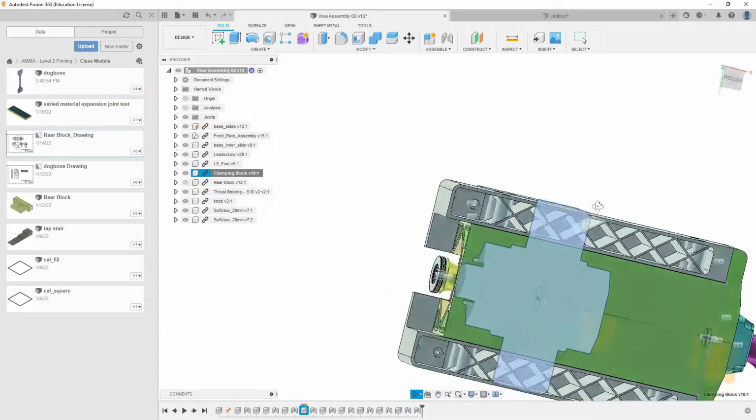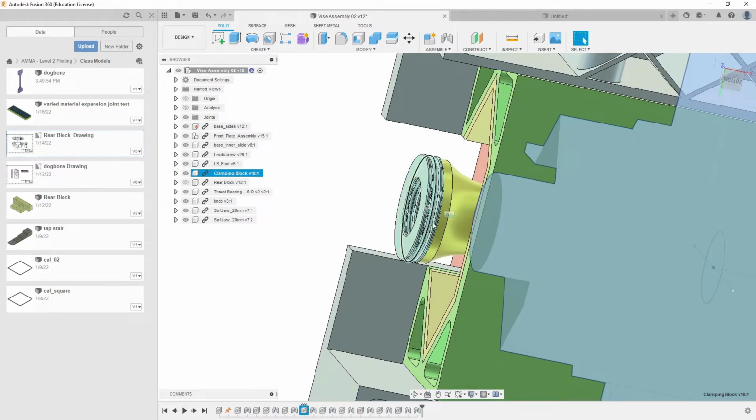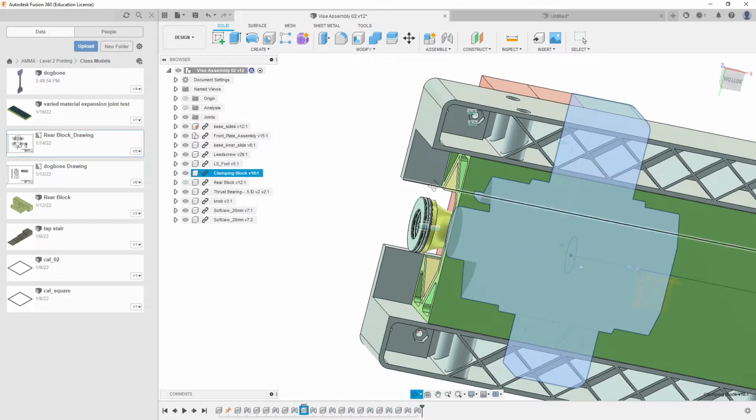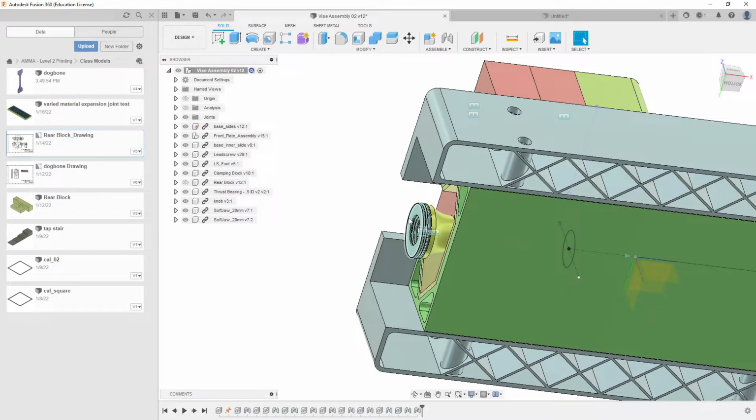Now, I also knew that this back portion here is going to have something for this lead screw and thrust bearing to anchor onto and push against. Now, talking about the forces that are on this mill vise going back and forth, we are going to have forces along this lead screw in both directions. So if we're opening it up, it's going to be pushing against one side. If we're clamping it down, it's going to be pushing against the other side.